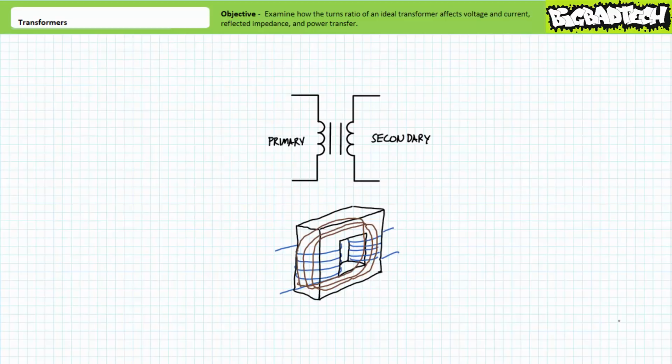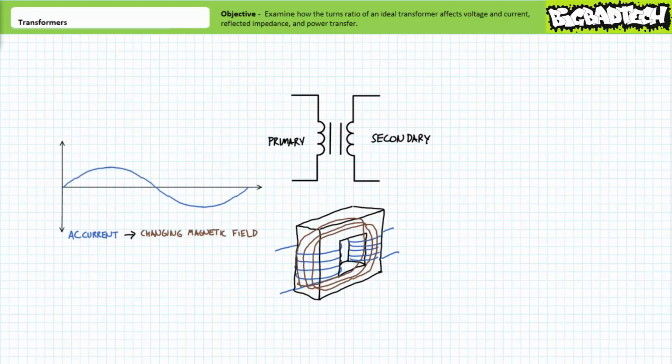I'll come back to correct this simplified diagram in a later lecture examining losses in non-ideal transformers. Before moving on, let me remind you that transformers necessitate AC voltage, something that cyclically varies both magnitude and polarity to function, since a changing magnetic field is a property essential to the induction process. DC, in contrast, is characterized by a steady-state value of a fixed polarity, meaning DC does not innately carry a changing magnetic field, meaning it cannot be readily transformed.